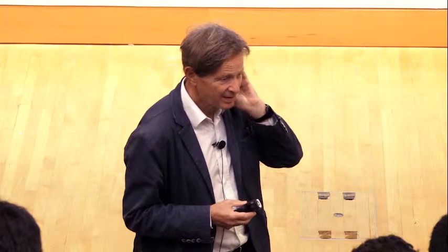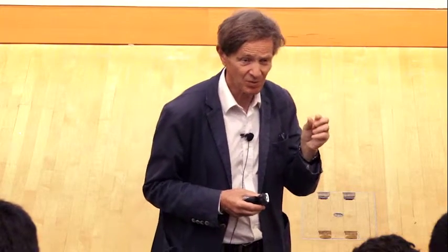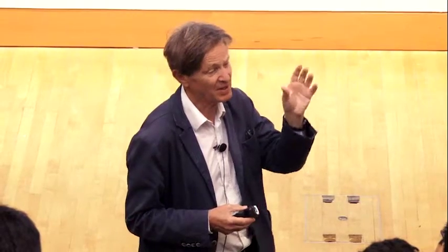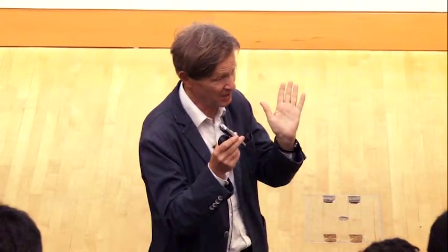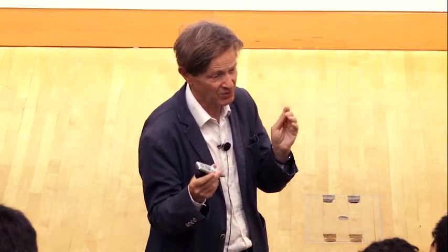Yeah. One more question. You did mention that there was a bluff body in the flow. Is that just the central body for the vanes, or did you put a different bluff body intentionally over there? No, we placed this central body because at first we thought we would have a hard time stabilizing purely aerodynamically. But afterwards we found that it was quite possible.